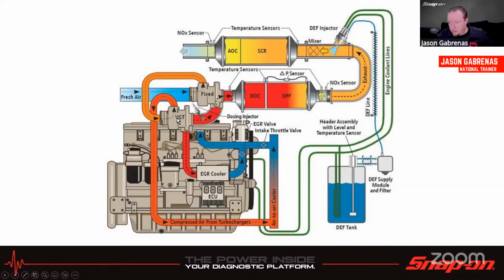Like we said, we can use that to control emissions there. We also have the EGR, and the EGR, there's the valve, and there's the cooler right there. And then we also have our catalyst and our diesel particulate filter right there. There is a differential pressure sensor that goes between the inlet and the outlet of the DPF. We'll talk more about that in a little bit.